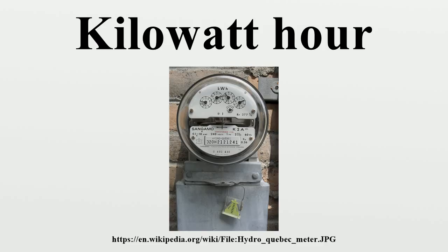The energy content of a battery is usually expressed indirectly by its capacity in ampere-hours. To convert watt-hours to ampere-hours, the watt-hour value must be divided by the voltage of the power source. This value is approximate since the voltage is not constant during discharge of a battery.